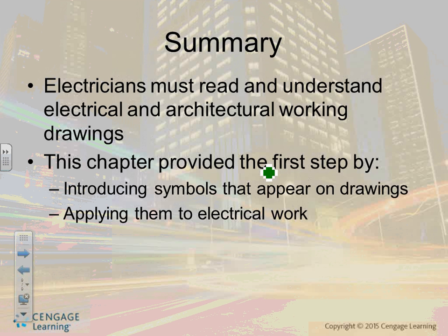Let's go, please, to page 37. There's a raceway symbol on page 37. Preferred symbol and description. Can you guys see how they do it on page 37? You see where it says a line? The line means conduit concealed in finished area, exposed in unfinished area. That's some of the ANSI symbols they use for conduit.